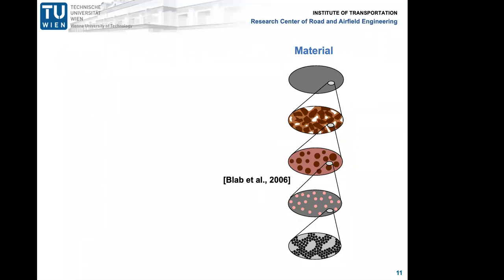Based on this concept, I mentioned that we started to develop such a multiscale model for asphaltic materials 10-15 years ago, and we have extended the first multiscale model in different stages. The first multiscale model for asphalt was characterized as depicted here in this slide. The asphalt was characterized by four what we call observation scales. The bitumen scale on the bottom here, with asphaltene and maltene morphology.